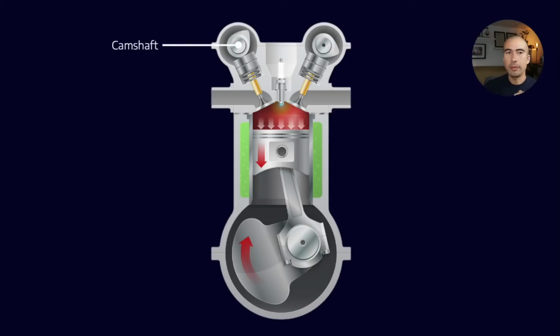If we start from the top, we've got the actual camshaft. It's not necessarily the shaft itself that needs to be lubricated, but the bearings certainly do. They're usually journal bearings and would experience hydrodynamic lubrication. Then we've got the cam lobes, which are often under extremely high load. The sliding and rotational motion between the cam lobe and the cam follower is a particular area of concern, especially in highly loaded engines like a race engine or a drag race engine.